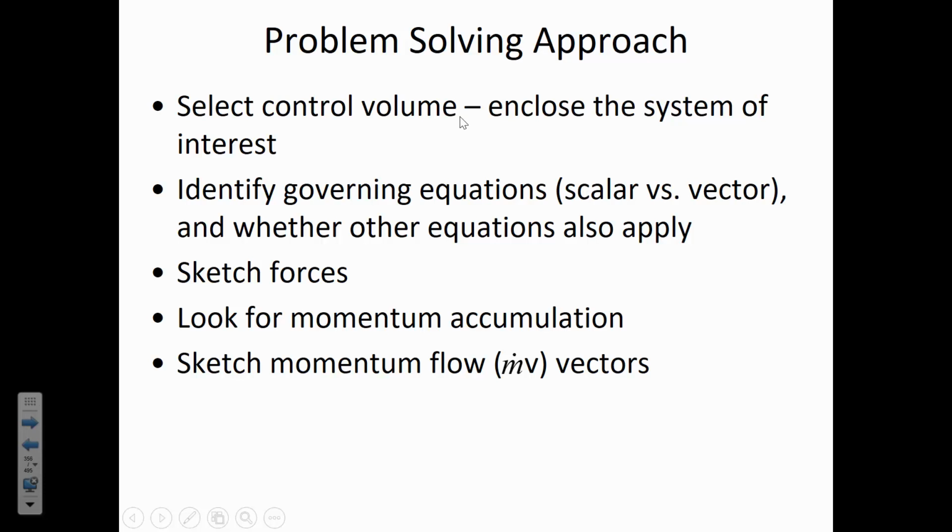There will sometimes be combinations of equations where we'll have a problem with momentum that also has a Bernoulli's application. One illustration of that that comes to mind would be if we had a system that was a nozzle and there's a jet of water coming out and we're pushing on a plate here with some force to pressurize.